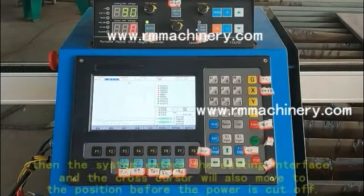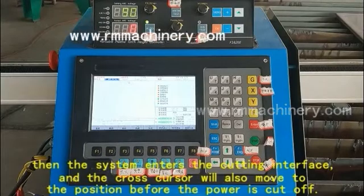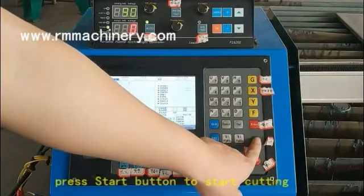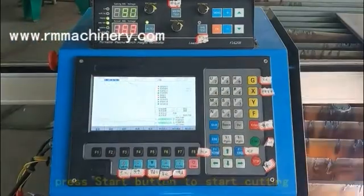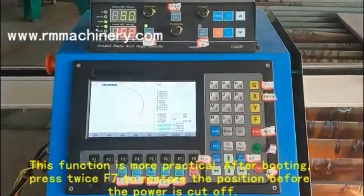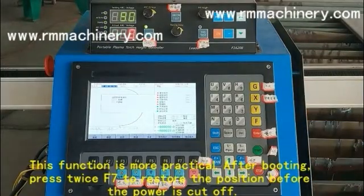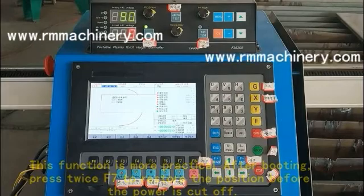Then the system enters the cutting interface, and the cross cursor will also move to the position before the power was cut off. Press the start button to start cutting. This function is very practical. After booting, press F7 twice to restore the position before the power was cut off.